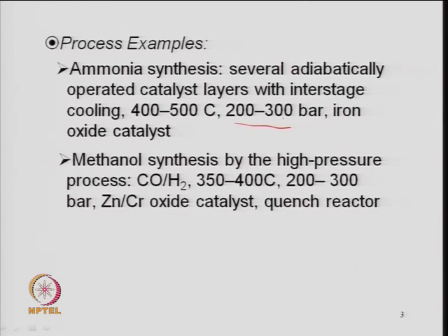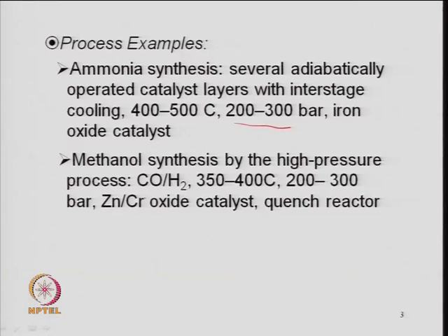Similarly, in the methanol synthesis also, generally this is a kind of Fischer-Tropsch reaction, where carbon monoxide and hydrogen are reacted, and we get the methanol, very important process for production of methanol, and especially from coal. So, coal converts to syngas, and then one can get this synthesis gas. Here again this copper zinc based catalysts are used in the system, and reaction is exothermic reaction. So, Fischer-Tropsch reaction is again an exothermic reaction. So, either a slurry type bubble column type reactors can be used, or these kind of multi-tubular reactors whenever the reaction is exothermic, because the control is easy in these cases.